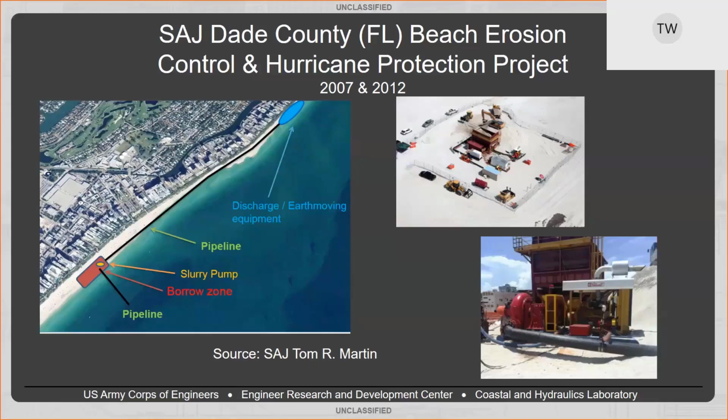Do these numbers include mobilization, demobilization, permitting, et cetera? What we saw was for the dedicated dredges, the numbers that we gave you for Hillsborough, we pulled off their dredging for the 12-inch pipeline dredge. They're pumping about $13 a cubic yard. Then you go out to, say, Santa Cruz, where they bought a new dredge back in 2016. They're pumping it for $5.86 a cubic yard.